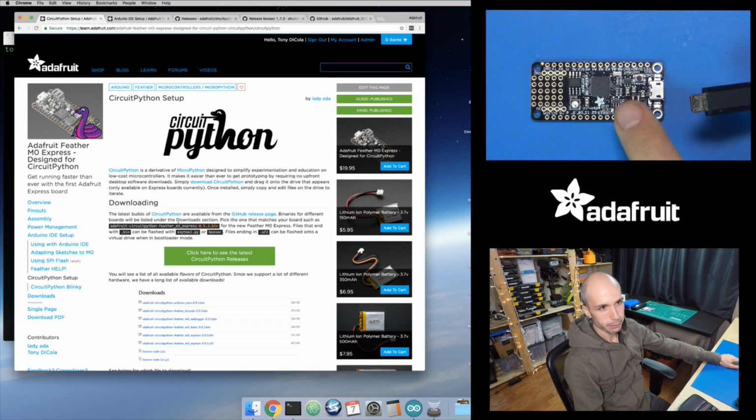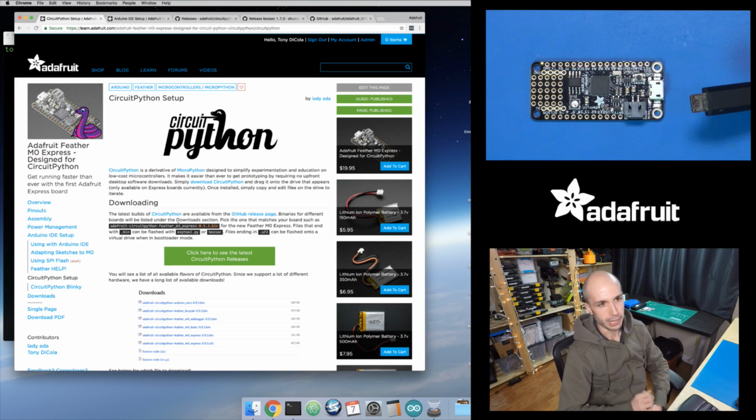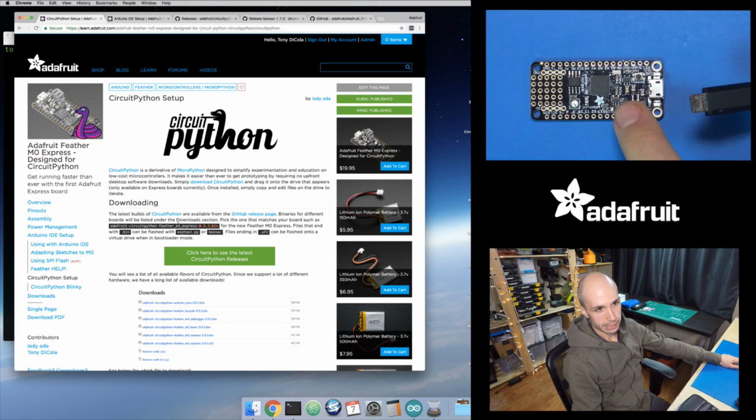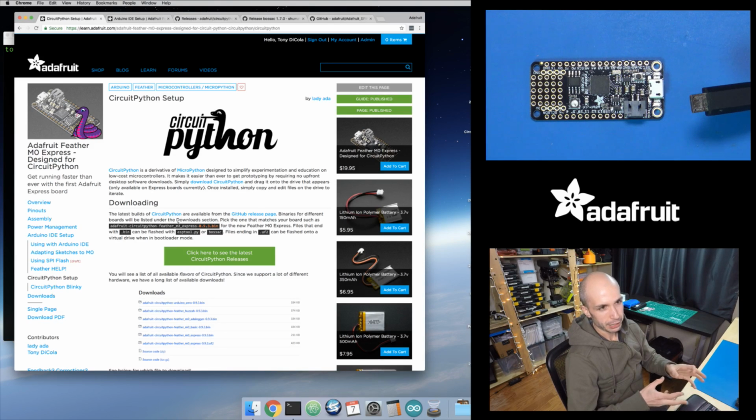This is another thing that's a little bit different about the Feather M0 Express board. It's shipping with a bootloader that's more advanced than the bootloader that we've shipped on the other M0 Feather boards. And this one's actually really cool. It has a special USB drive mode. If you've loaded CircuitPython onto a SAMD21 or a Feather M0 in the past, you've probably had to use a command line tool, this BOSSA tool that just talks to the chip and sends it all of the data. It works, it's fine, but it's a little bit tricky sometimes, and you have to install some software to use it. So we were looking at, is there an easier way to use this with custom firmwares? And I'll show you something neat.